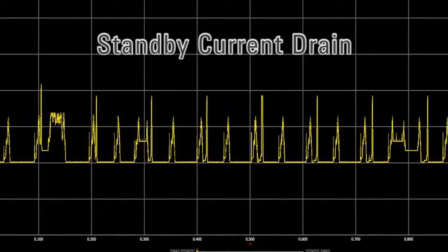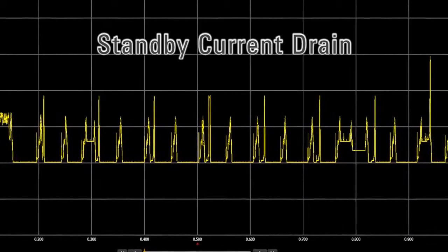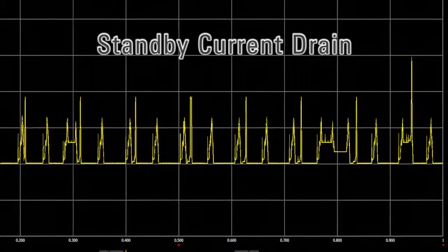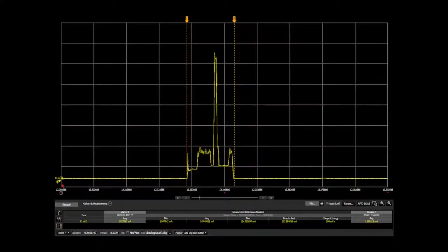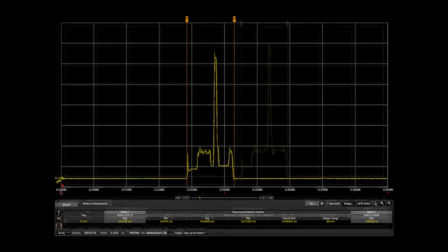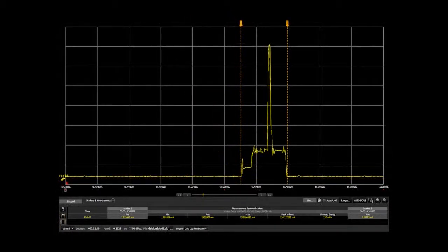The difference in average battery current drain before and after a design change is the net impact of that change. The objective is to try to correlate the effect of a design change on the current drain activities related to that change. One approach is to manually scroll through the data log and examine the amplitude and duration of specific current bursts related to the design change. Not only is this process time-consuming, but may result in incorrect conclusions unless many events are accurately recorded and averaged. And each time you make a design change, this tedious process must be repeated.